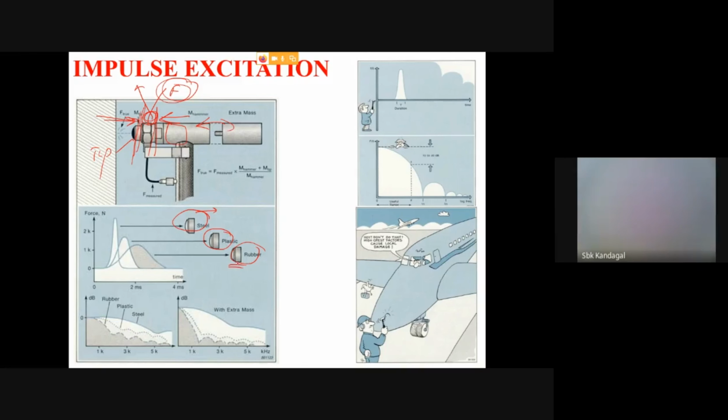Okay, so there you can find the natural frequency of the mridangam, which has a very thin rubber or a thin skin, and on the ghatam you have to find out the natural frequencies of the shell mode, etc. You can use soft rubber, etc. So this is how the tips are changed, and from here the output goes to the conditioning amplifier again. Okay, I will tell you why the conditioning amplifier is necessary, because the signal coming out of the force transducer has got a high impedance, and you have to reduce that to a measurable level for either the oscilloscope or a data system. You can use the conditioning amplifier.